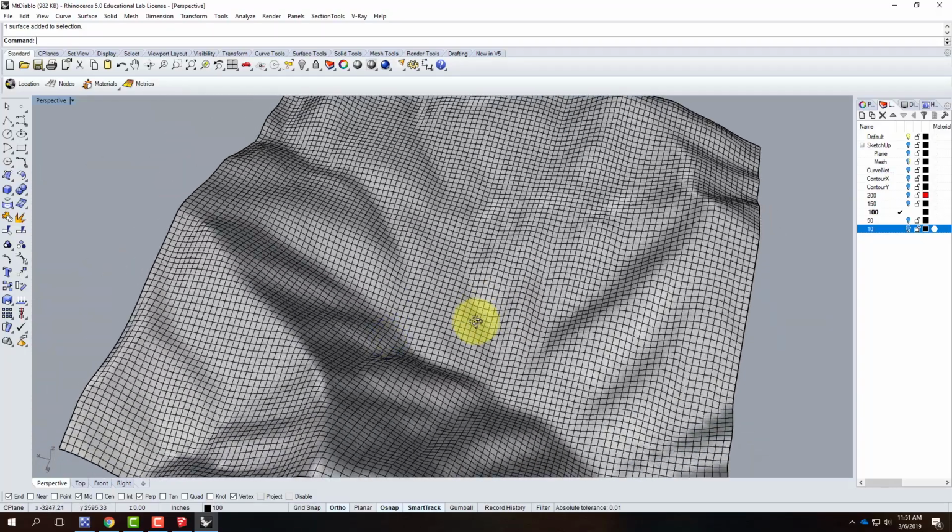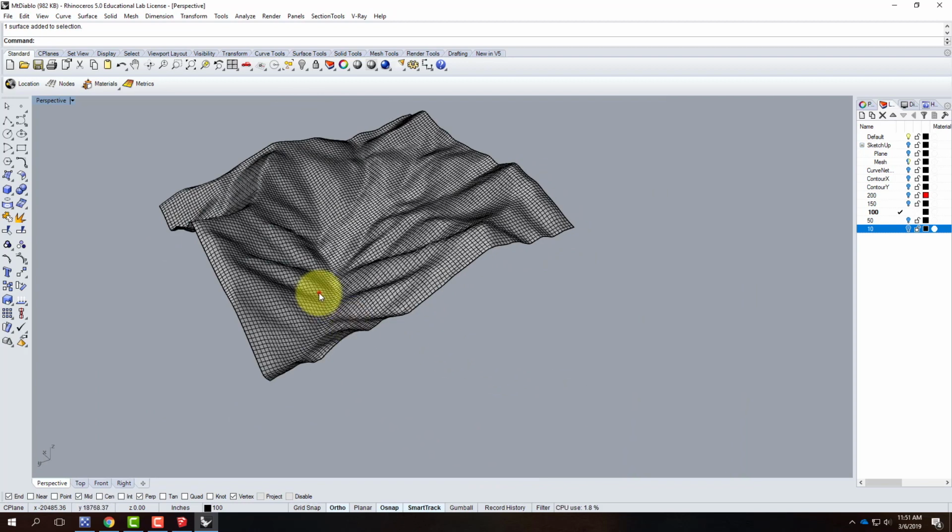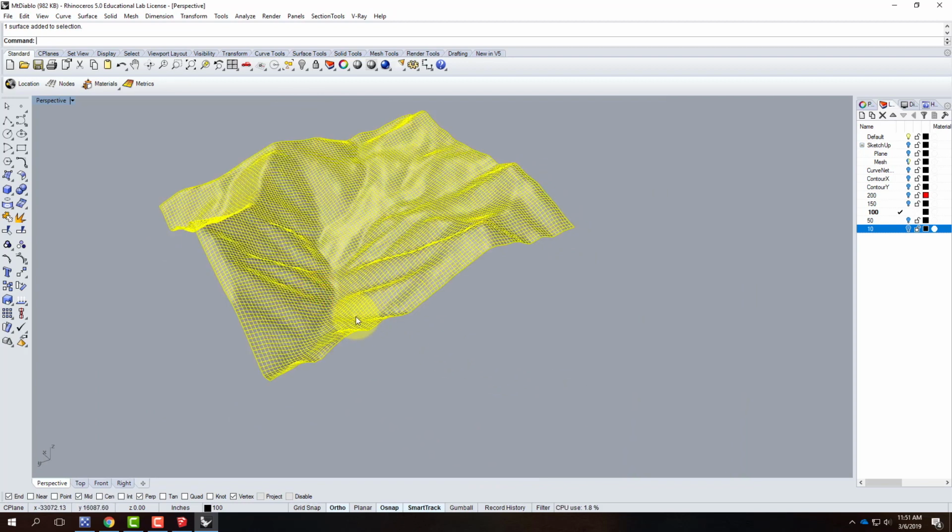We're going to do a couple more things with this before you're done for the day. And of course, this will come back. We'll repeat all these steps again in a slightly more organized fashion next class. I'm going to go ahead and slice up this terrain as a bunch of topo lines. So instead of doing my contour in the X or in the Y, which I've done, I'm going to do a contour in the Z to slice it up like it would be a topo map.